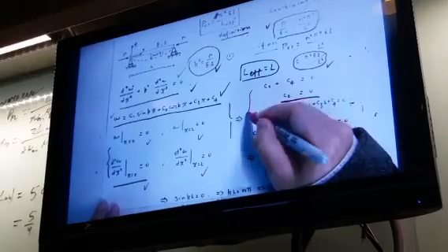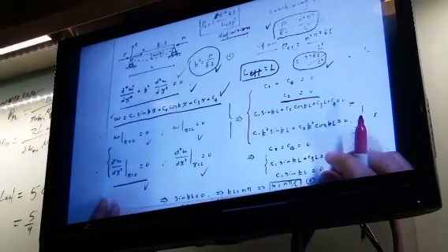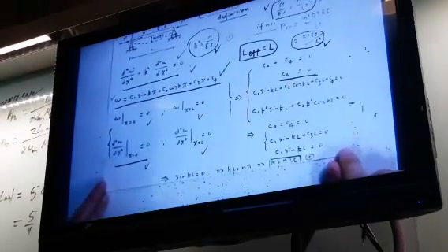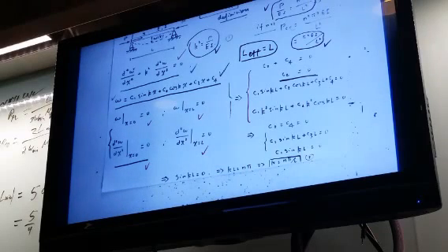And then you have four equations. So basically, when you're trying to solve for the coefficients C1 until C4, you can form a 4x4 matrix. Okay? So to have a non-trivial solution, the determinant of that matrix has to be 0, and you can solve for K. K is a function of P.